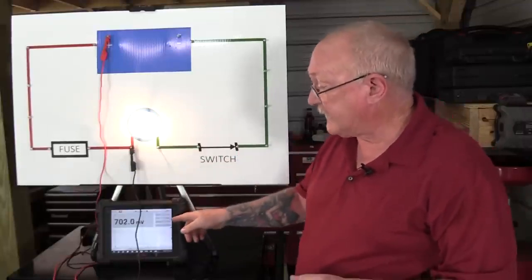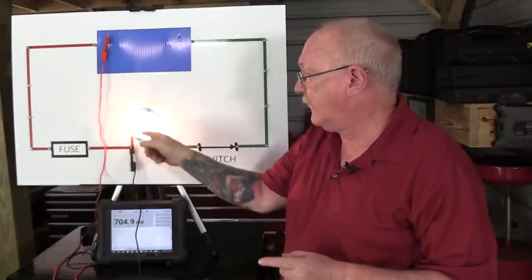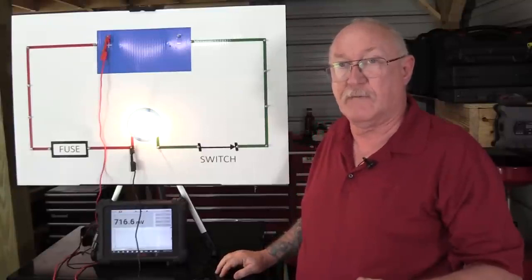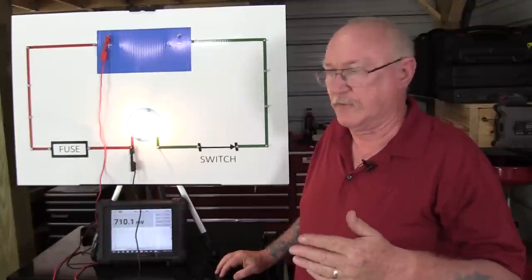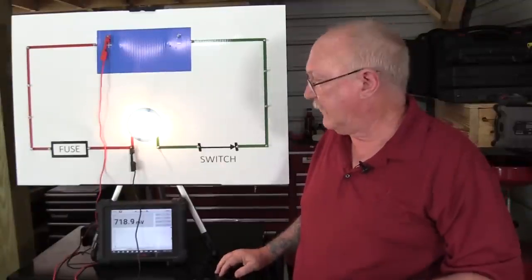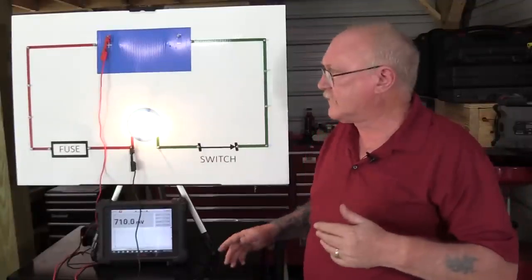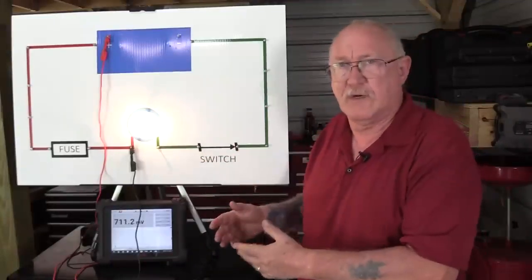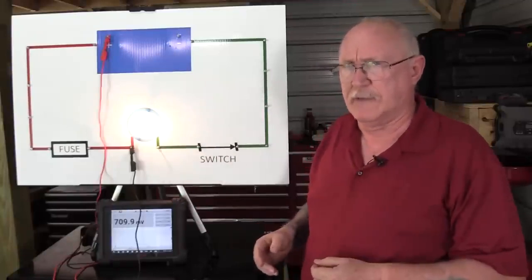Now take a look here. We got 700 millivolts. That's the amount of actual voltage drop that I have from here to here. Is that similar to what we started off when we were looking at it just a moment ago? Between the 11 and some change and the 10.9, right? That was a little bit more, maybe a volt or so, but very, very close to what we're looking at in terms of drop. Now, this makes a great testing method, don't you think? If I had a source of unwanted resistance, well, that would be another mouth to feed. According to Kirchhoff, it would take away from what I'm getting here. Well, we'll take a look at that in a moment.